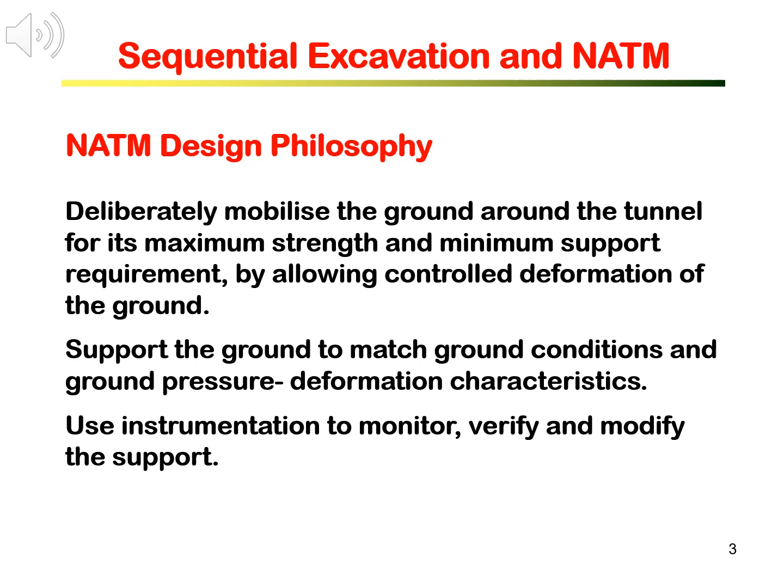Primary support of the ground is installed having load deformation characteristics appropriate to the ground condition, and the installation is timed with respect to ground deformation. Instrumentation is installed to monitor deformations in the primary support system, as well as to form the basis of varying the support design and the sequence of excavation.